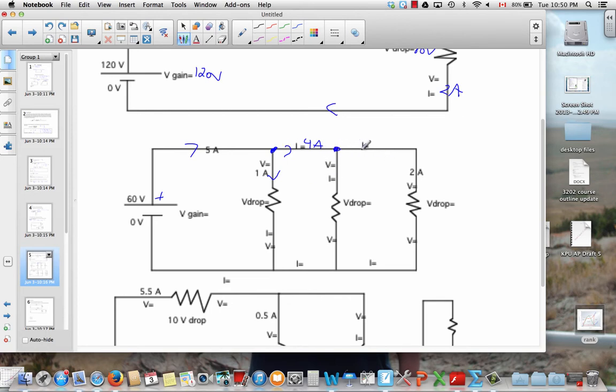It seems at first that both of them are unknown, but if we look over here, we see there's 2 amps of flow at that point. Working backwards, there had to be 2 amps of flow there. Then by currents in equals currents out, there must have been 2 amps flowing down this way. So this is still the 2 amps, and it's going to recombine with the 2 amps flowing in that wire. So you'll have 4 amps flowing to the left. There was 1 amp flowing down here. The 1 amp will combine with the 4 and give you 5 amps of flow out here.